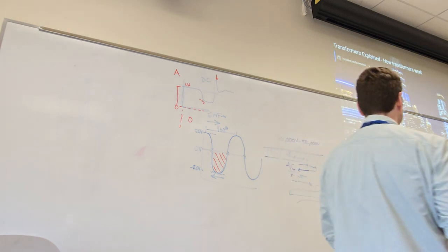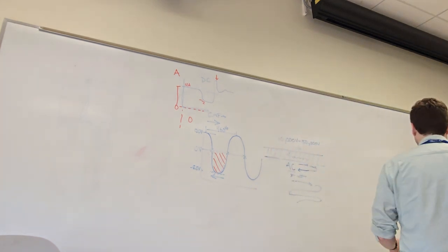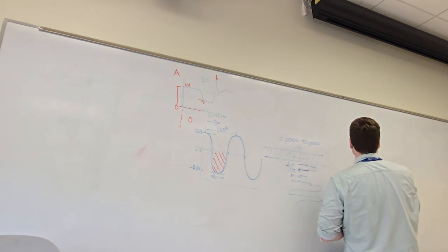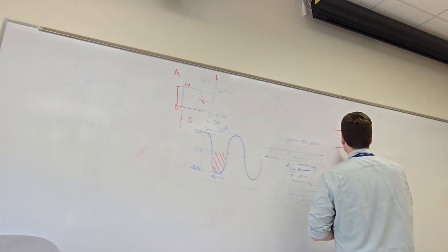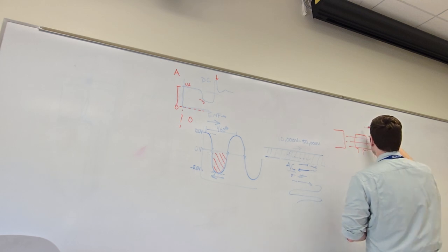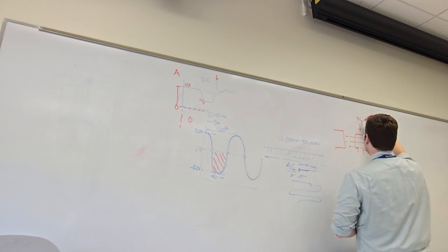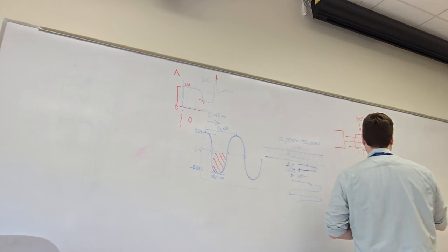All right, so just to restate a little bit, what we said before was that when we have an armature, or a square-ish coil, inside of a magnetic field, when it's in one position, it will see 100% of the possible force coming from that field between the two magnets.